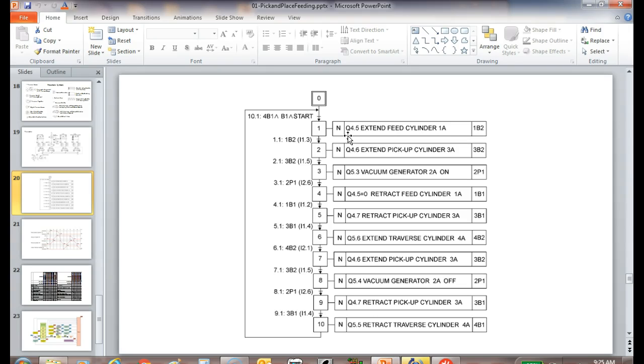Allen Bradley uses O for output and I for input. Siemens uses I to identify a PLC input, and it uses Q to identify a PLC output. So the PLC address is actually I1.3, line 1. Yeah, these are inputs. So inputs are on the left.